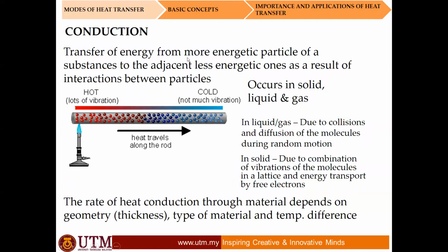So what is conduction? It's basically a transfer of energy from more energetic particles of a substance to the adjacent less energetic ones as a result of interaction between particles. So the energy transfer is due to different temperature, caused by vibration of particles in a solid.